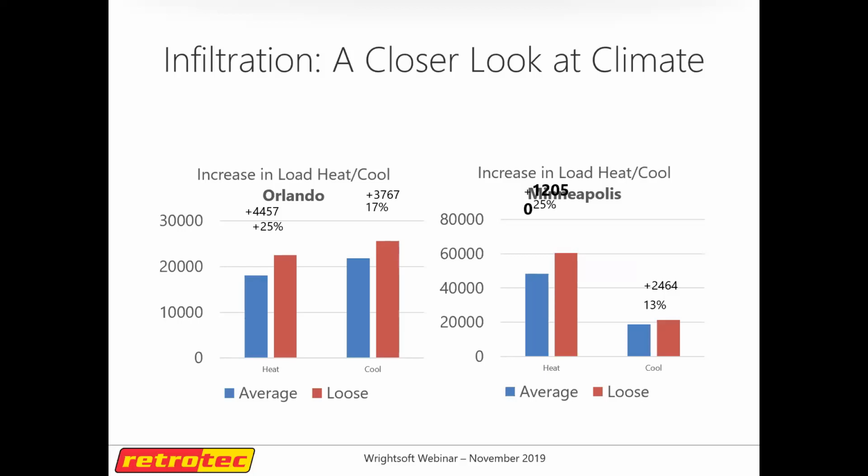That's why load calcs are such an important issue. And the amount of moisture removal you have to do has a significant impact on what type of system and what actual system you pick out, because it has to be up to the job. When you look at the system you selected, not all systems remove the same amount of moisture. And if you have more moisture to remove, you increase the load.